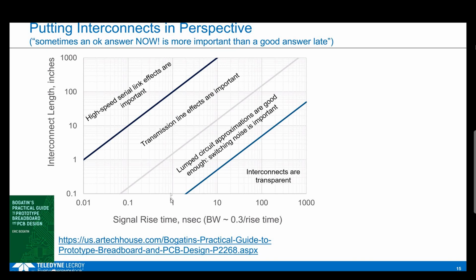And then if we're talking about a short rise time and longer and longer interconnects, when we start talking about nanosecond edge and 100 inches long, then we still have all of these problems in those systems. And in addition, we also have the high-frequency properties of the interconnects, the problems that arise in high-speed serial links. This is about the losses in the interconnects.